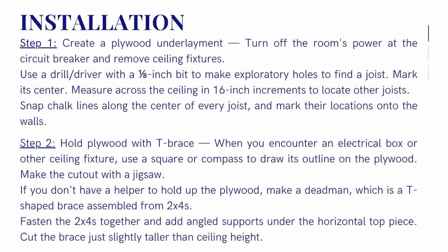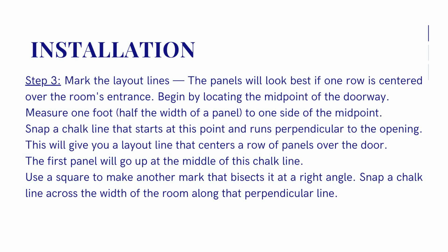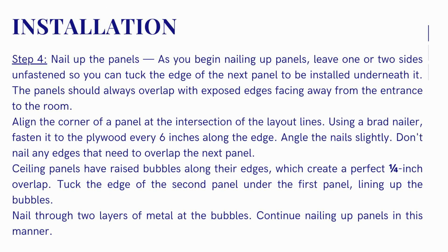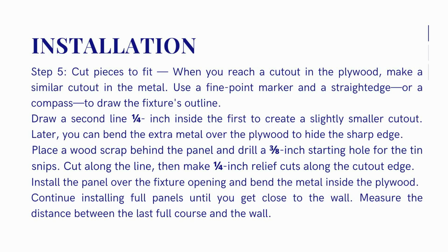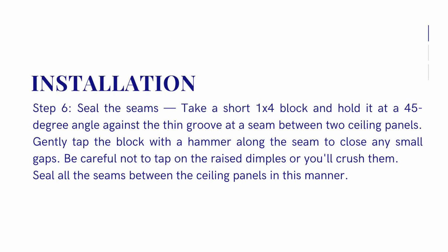The properties of metal are durability, humidity resistant, fire resistant, and demountable. Metal ceiling panels are all antibacterial tiles which are press-formed from aluminum alloy series 3000 or mild steel and factory finished with an electrostatically applied polyester powder of 70 to 90 microns. Suspension components are made from galvanized steel or pre-painted steel or aluminum.